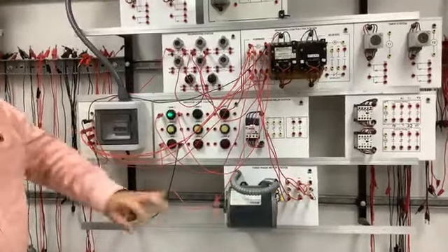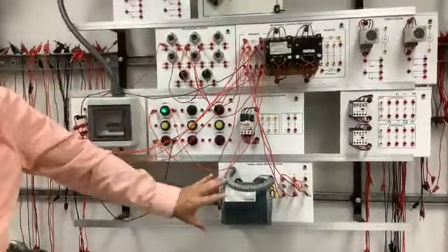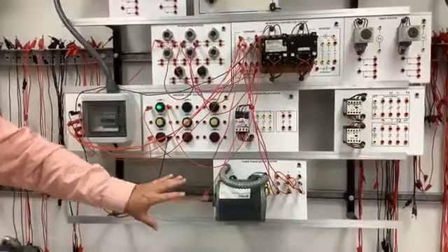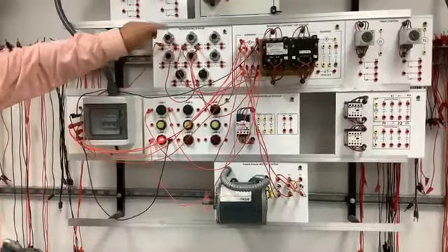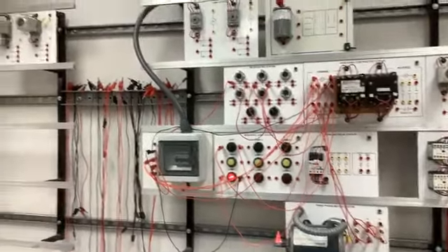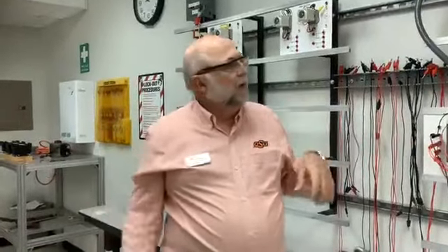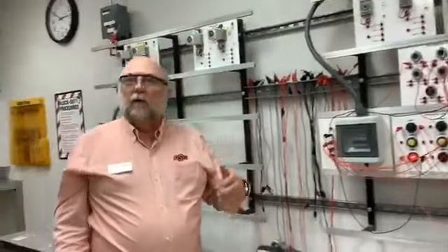See, it's operating, and this is three-phase power. We have single-phase power with the control circuit controlling a contactor, which then puts power to our motor, okay? This is one of the simpler circuits that we're talking about. Start-stop, we have a forward and reverse. Maybe want to go in the forward direction, or switch the motor to go in the reverse direction. We can include different things in there, from a timer to keep it from going from forward to instantly in reverse. You want there to maybe be a 60-second delay time till it spins down, right? So all kinds of variations in this.